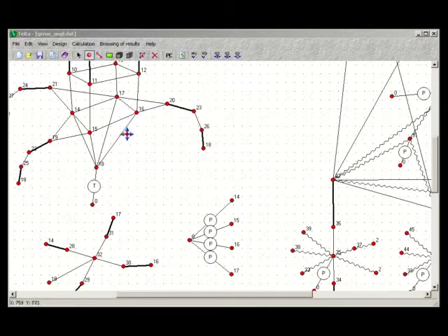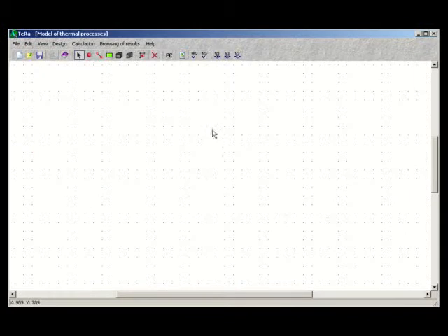Thus, the product is divided into conditional isothermal volumes. For example, elements of product construction in which it is necessary to define temperature, air volume inside the block, environment, and etc. To the allocated conditional isothermal volumes, we put conformity blocks of the thermal process model.